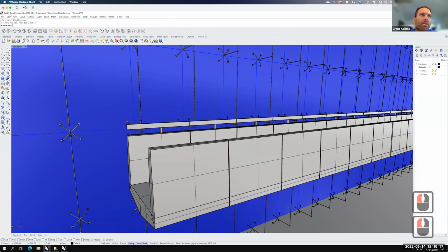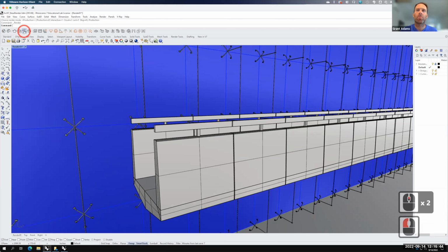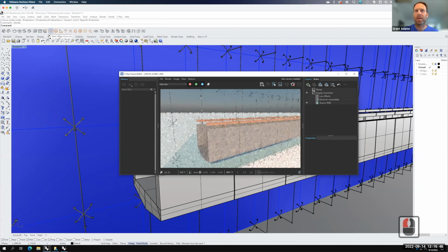Update. So this ends up being a really powerful tool because we can get approximate geometry, bring it into a main scene for rendering, and then make changes to it after the fact. So you saw I just added that railing, but it's applying to every one of the block references that I have. So I'm only making the change once, and it's populating across many more pieces. So we could do another little rendering here. And now we're going to see that wooden rail as it goes along.